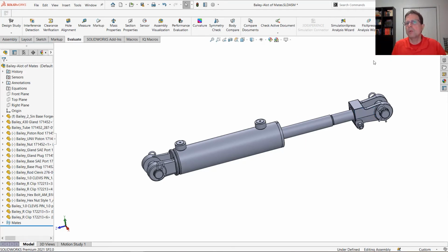So how do you reduce the number of mates? There are 2 solutions. One is restructuring this assembly. So I'm going to create 2 sub-assemblies to capture the static mates, and I'm going to apply the dynamic mates only between those 2 sub-assemblies. I imagine the piston is going to be a good candidate for a sub-assembly. In this case, I have certain components that belong to the piston that are kind of hidden there, so I'm going to show you one of the tricks that I'm usually doing.